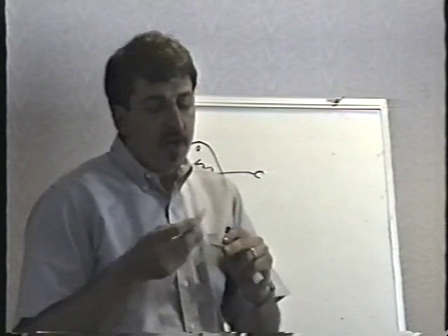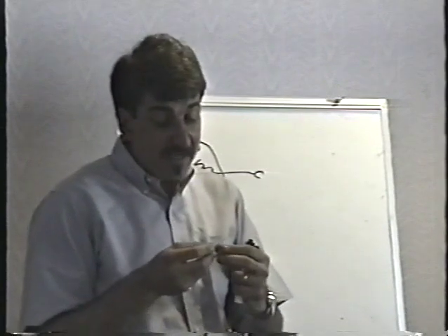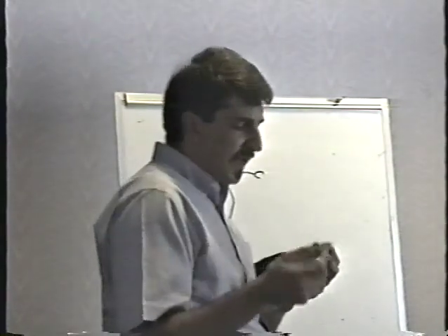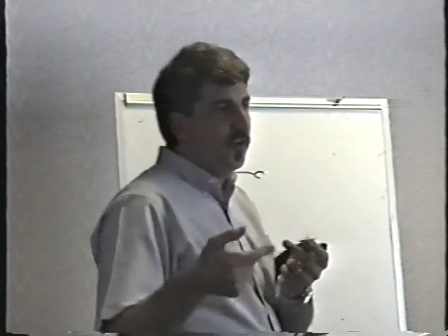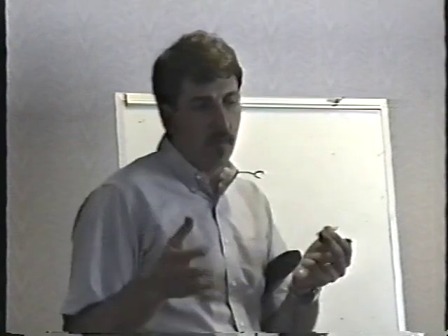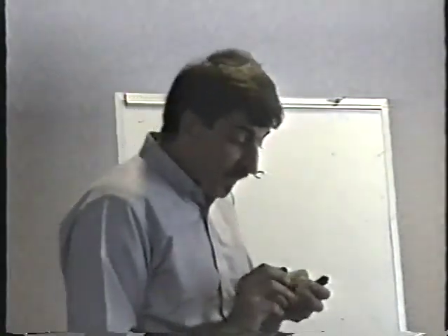When you see it, it doesn't mean that your transistor exploded or anything. That's perfectly normal. You're supposed to put new heatsink compound on whenever you change a transistor. I don't, because I was trying to be very professional for a while, and I carried a little tube of it around in my toolbox till my long nose pliers skewered the tube and got this white crap all over my tools. I'm sure whoever stole my tools still has it all over them because I couldn't get it off. So anyway, be aware of that.